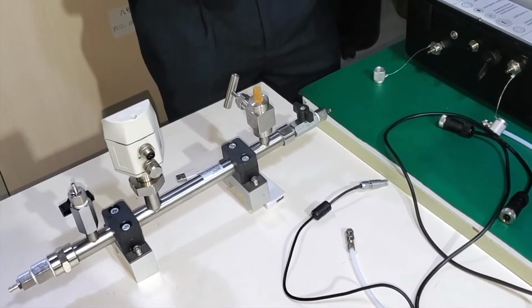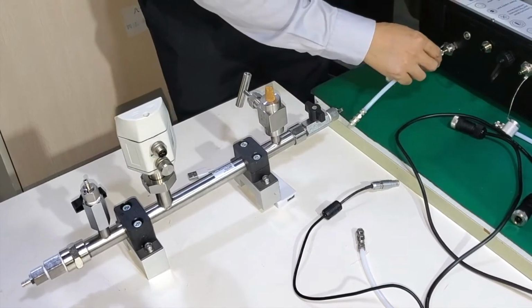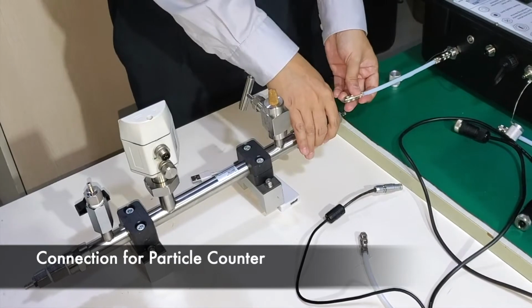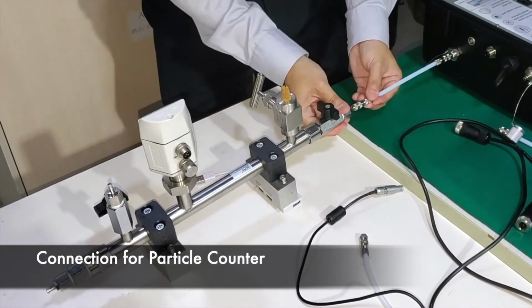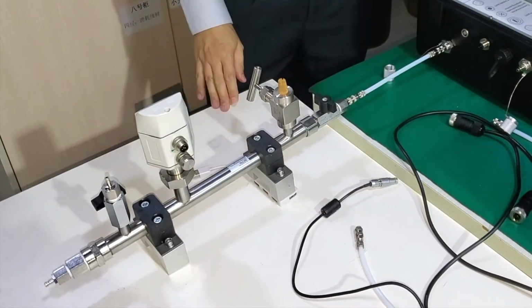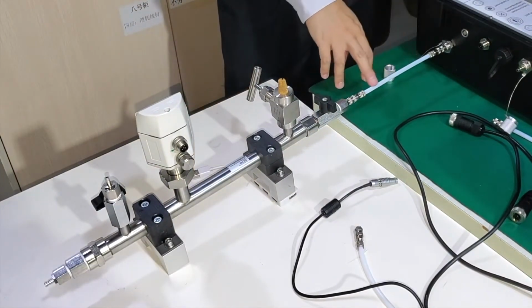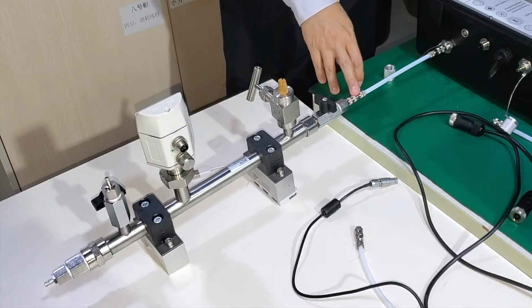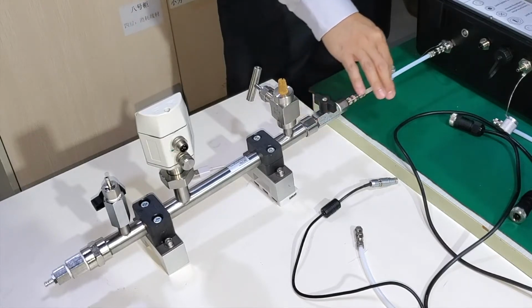Once all caps are off from the device, we will use our first small Teflon hose to connect to the first inlet, and this will help us monitor our compressed air particles. The air that runs through the isokinetic device will go directly to our particle counter, and this will let us know particles that go from 0.1 microns all the way to 5 microns.